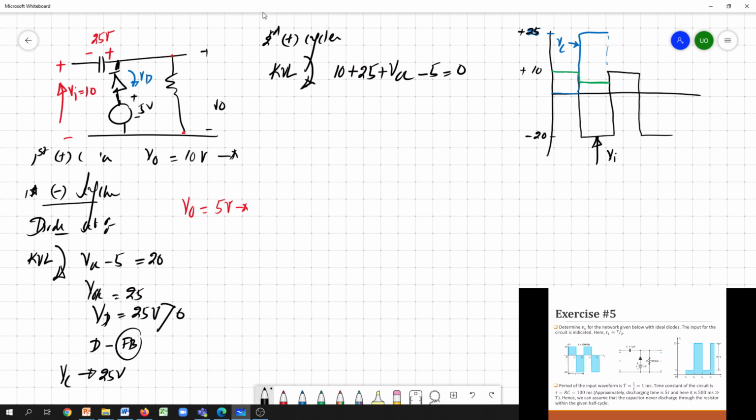This is 0. So then this open circuit voltage is actually 35 minus 5, so it's minus 30. So this is the actual voltage across this diode, minus 30 volt, which is less than 0. So the diode is definitely in reverse bias.